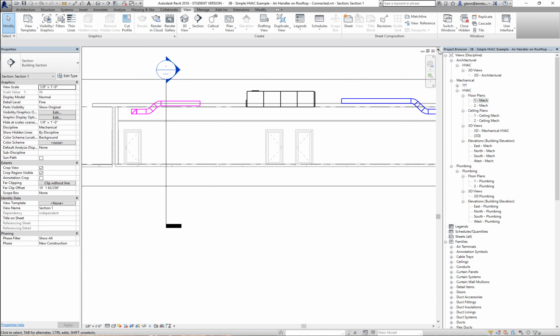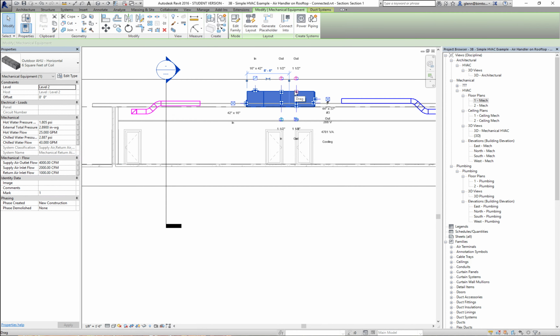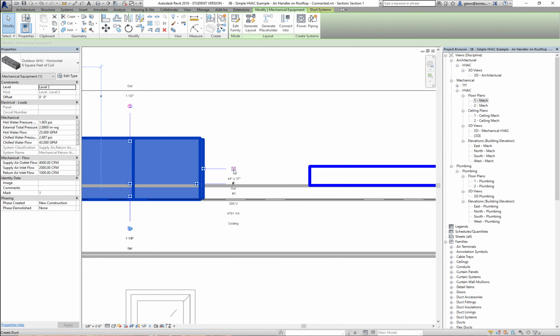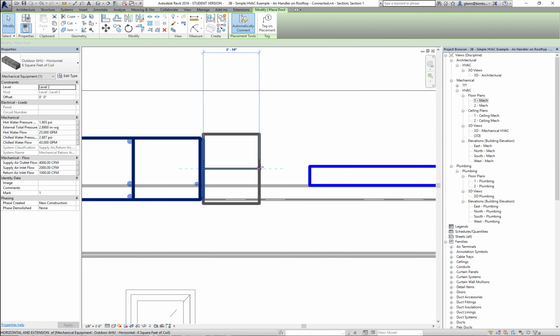So let's start by just making the ducts that come out of the unit. It's always useful to go through and have those first pieces just kind of hanging out and then try to connect things to them. So if, for example, I wanted to think about the piece of ductwork which is going to come out of the nose of the unit, over here on the right-hand side, let me zoom in there. What I can do is create a duct and pull out just a hair.